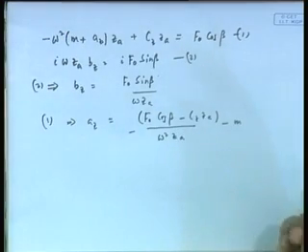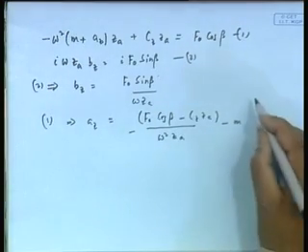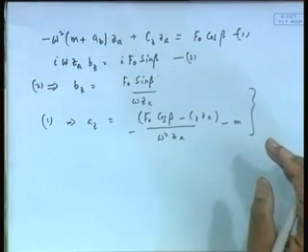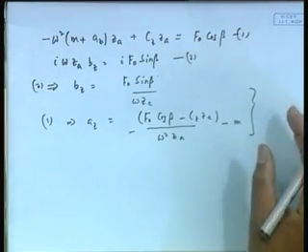You can work it out whichever way. So what I mean is that this is what is called the forced oscillation test, which you could do to find out basically your added mass experimentally. This is a very important test.